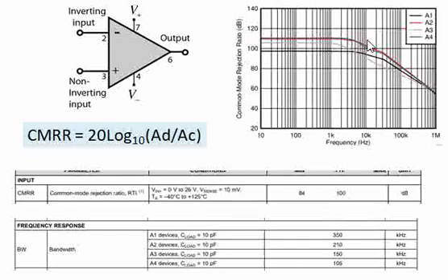For example, if you are selecting an operational amplifier and the CMRR is around 100 dB, that op-amp is very suitable to give common mode rejection and apply the gain over the differential signals. That's one thing a design engineer can keep in mind.